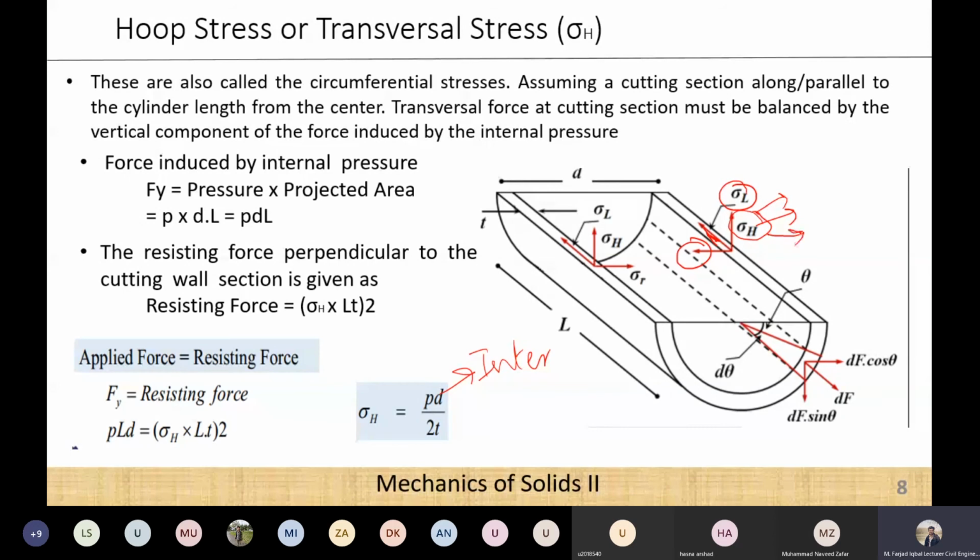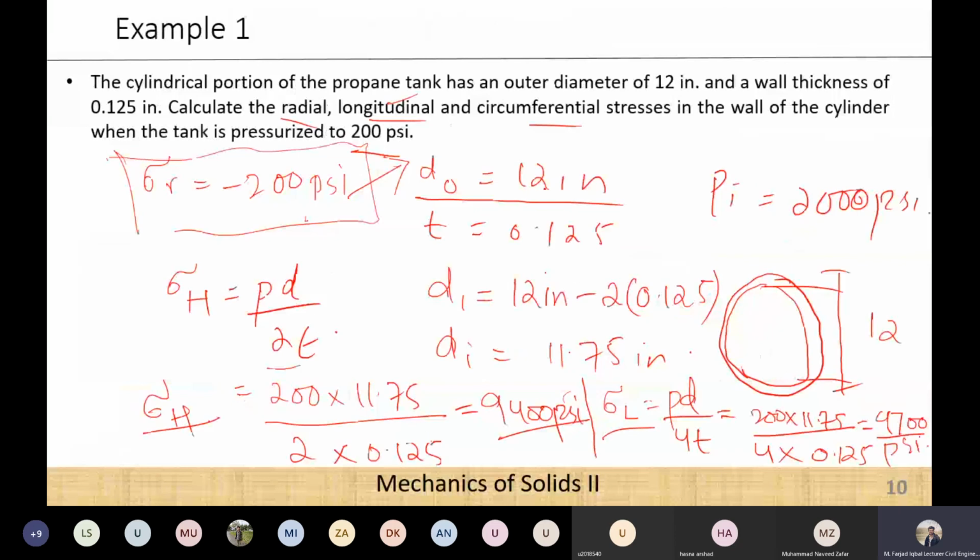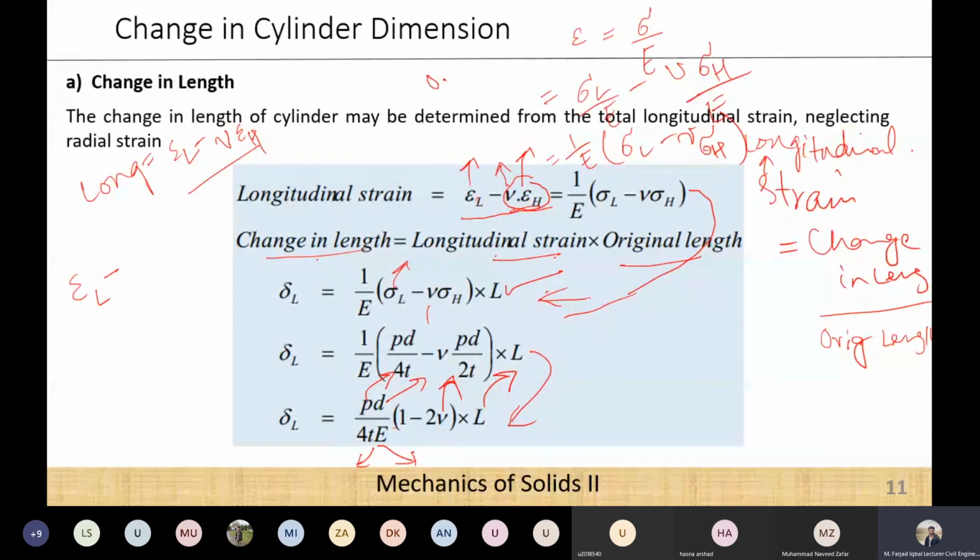And this small quantity has been determined to be multiplied by the Poisson ratio factor. For example, the Poisson ratio for a material is, let's say, 0.2, and the strain produced in the opposite direction is somewhat 0.001. When you multiply these two factors, you get a small answer. So the strain produced in the longitudinal direction will not actually be this value. It will be reduced by a factor mu times epsilon h. Have you got my point?